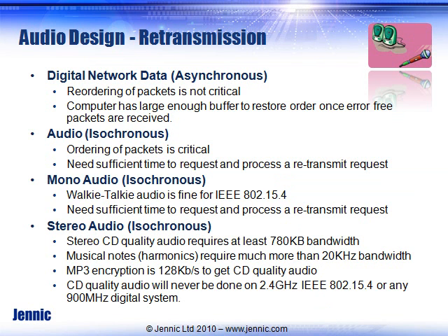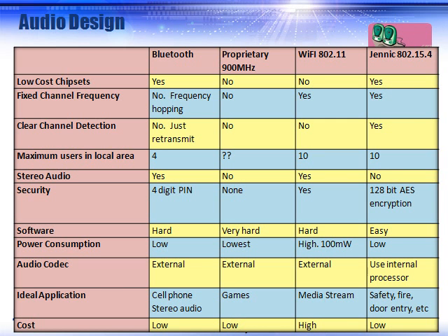Some of the other factors that are important are whether you're going to do mono or stereo. If you're going to do stereo and allow retransmitting, there is not enough bandwidth on a 15.4 radio, even if you do MP3 encoding. So our design is typically based on mono audio, which is great for tone quality audio, but if you want to transmit music in stereo quality, this is not the wireless radio scheme for you to use. But if you want high quality tone quality audio, this is a great solution to use.